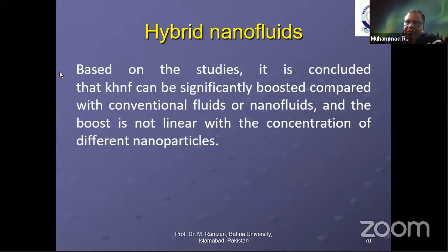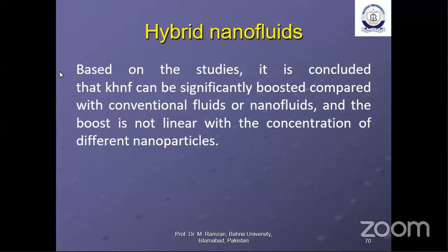One of the studies measured thermal conductivity of silicon oxide with the water and silicon oxide with the ethylene glycol, as compared to their value, the silicon and the copper with the water and silicon oxide with the copper with the ethylene glycol. Obtained results show that adding a small amount of silicon oxide nanoparticles leads to less than 2% enhancement in thermal conductivity of the fluid.